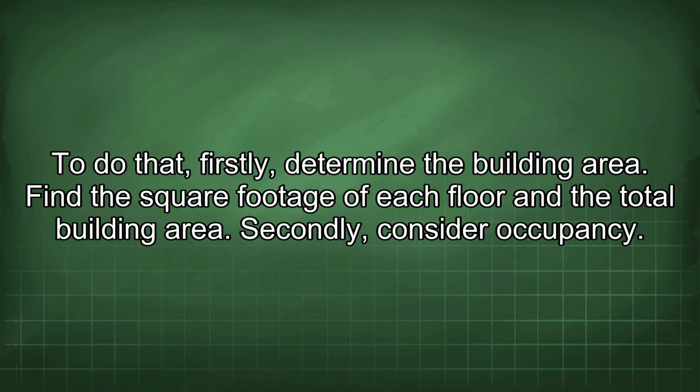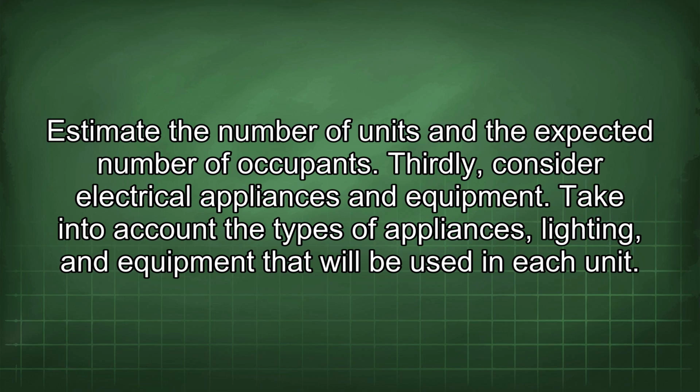Find the square footage of each floor and the total building area. Secondly, consider occupancy. Estimate the number of units and the expected number of occupants. Thirdly, consider electrical appliances and equipment. Take into account the types of appliances, lighting, and equipment that will be used in each unit.